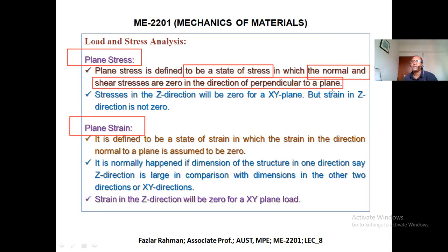Right now, we only load in the vertical direction. You might put your laptop or desktop by your monitor, right? So this is force working only in the vertical direction. But in some situations, say this is my cell phone, if I pull this way, that means I apply all the force in a single plane, but in the vertical direction there is no force, then we'll call it plane stress.